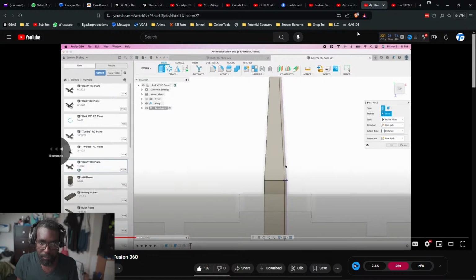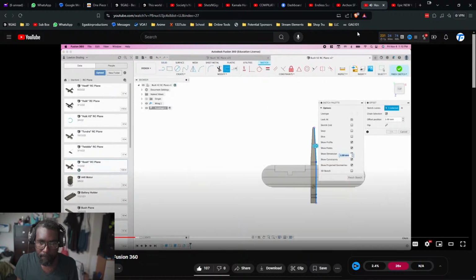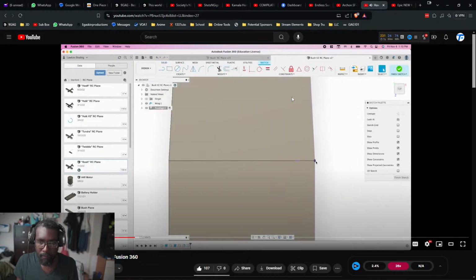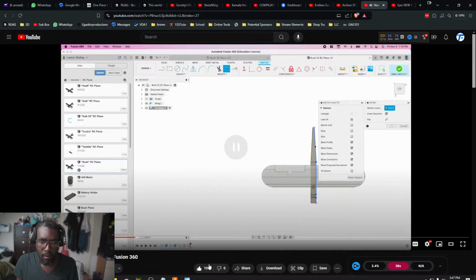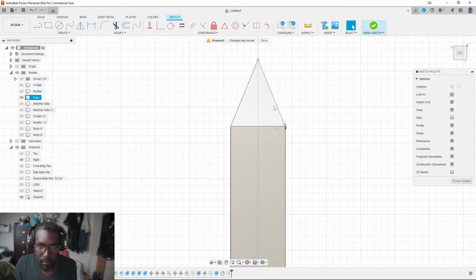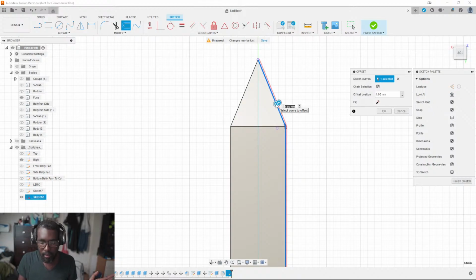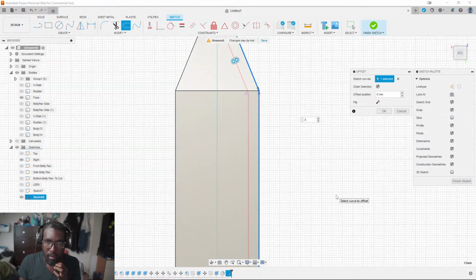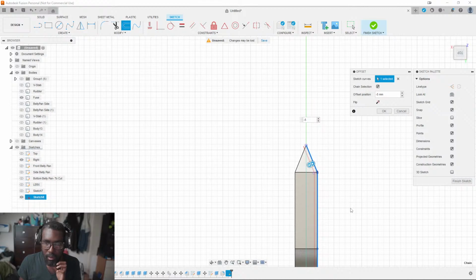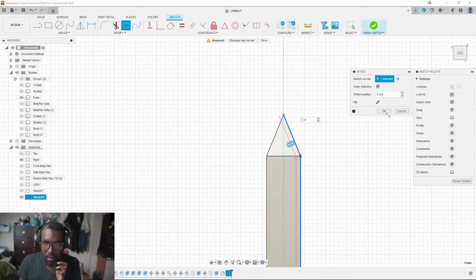Add end caps to this. Cool, and then okay, well, I grab everything, then do the fillet. Do the offsets, but can I do the offset without it? Hey, look at that. 5 millimeters. Whoops. Negative 5 millimeters. Alright, that's biting into the tip there.